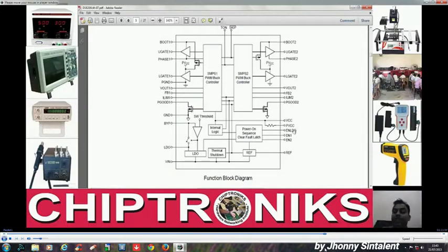That is, this is the logic inside this regulator IC, which will determine whether to generate 3 volt, whether to activate this SMPS1, whether to activate this SMPS2. So the power on sequence logic is inside, which gets started with EN1, EN2 and enable LDO, right? And what is soft start?